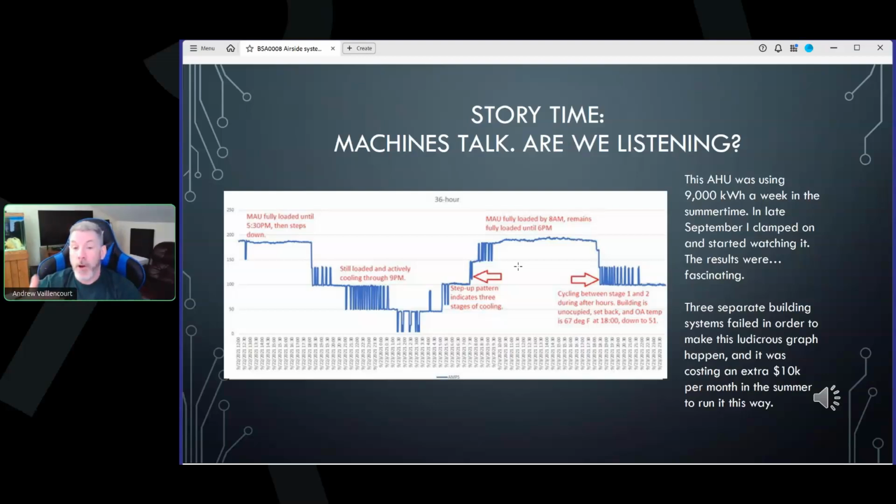The ASHRAE standards are already very generous with outside air, and they do that on purpose. They want people to have fresh air. ASHRAE doesn't get paid to choke people. For instance, they talk about CO2. The CO2 threshold is 1,000 parts per million. I tell you right now, that's the point where a human being might actually notice. And a lot of places are running 600 parts per million CO2 before their demand control systems kick on. That's good for nothing.